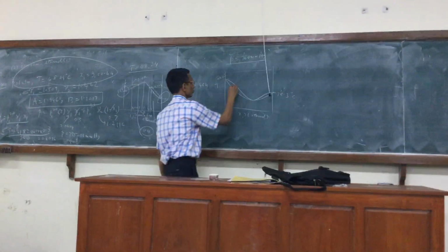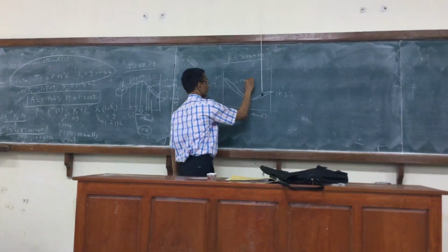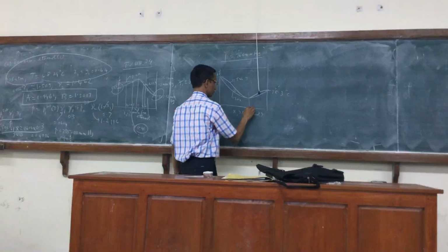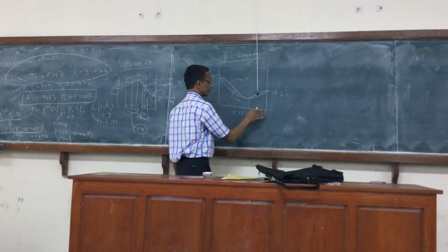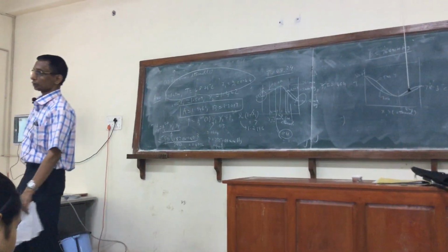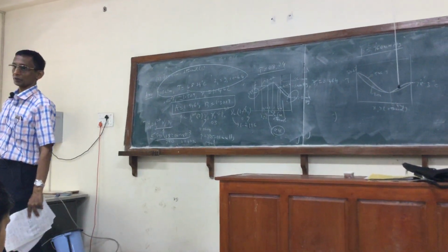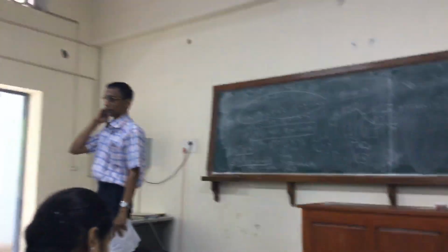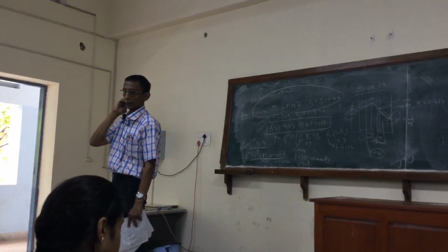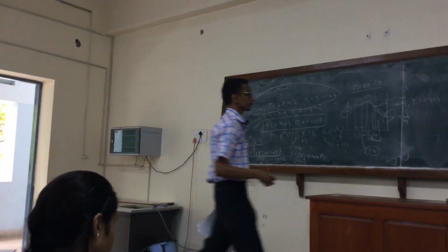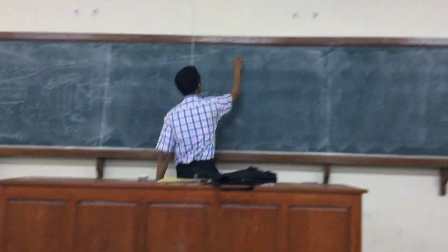This would be T versus y, and this would be T versus x. Again, this is 0.44. It doesn't look like that, but anyway, so this much you can draw. Now we have a choice again, either dew temperature or bubble temperature. In either case, it has to be an iterative procedure. It is illustrated already for the bubble temperature for the ideal case. Let's just see the dew temperature.